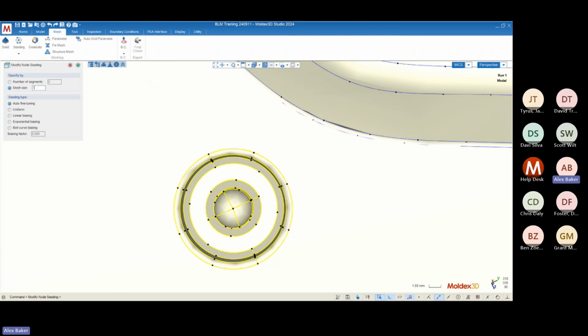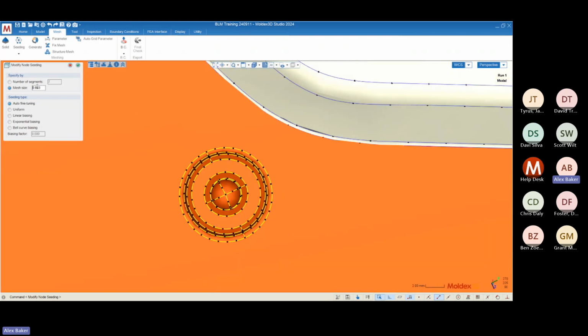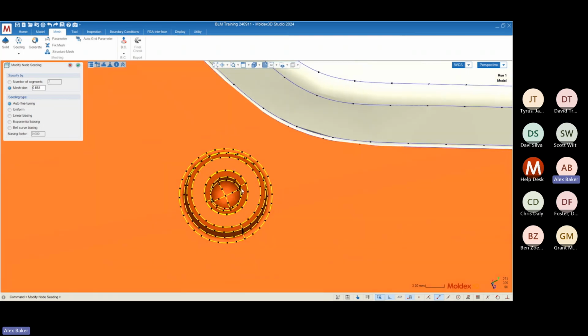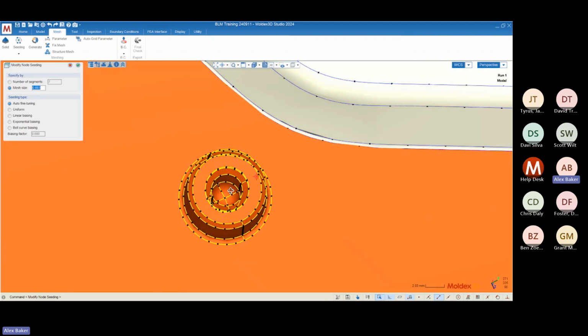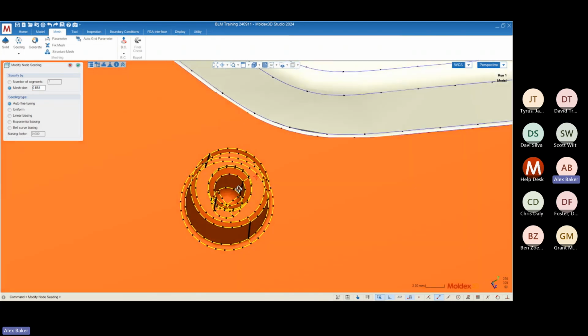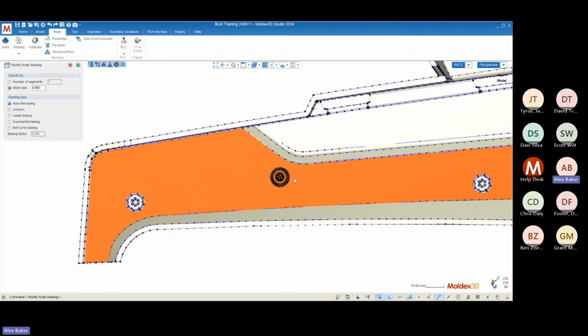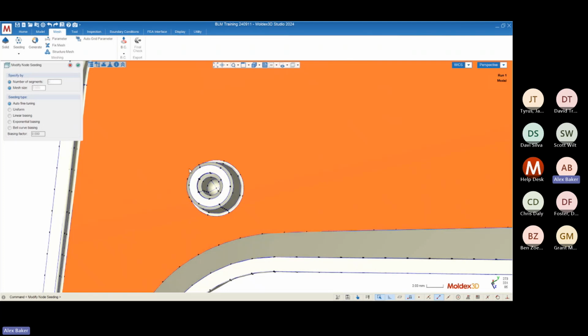And then I'm going to drop this to quite a bit lower. Let's say a mesh size of 1. Don't be too alarmed if it automatically applies a different value. The value that you apply is what each feature line is going to attempt to get to, and then the average of what each feature line actually gets to is the new value that shows up here. So don't be too freaked out if it automatically changes to a different value. It will always do that, but it will still try to get close to the value that you initially selected.